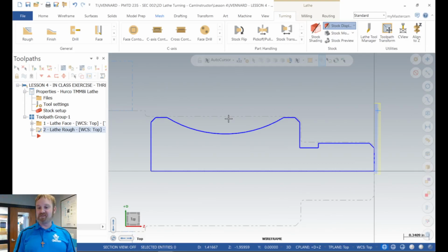A lot of times you've probably seen videos where they use them multi-directionally, meaning they'll come in, cut like this, then go right back and just keep going into the cut. That's another time to use one if you're trying to remove material really fast, since it doesn't have to go back and cut from the same side every time like a right-hand turning tool would.